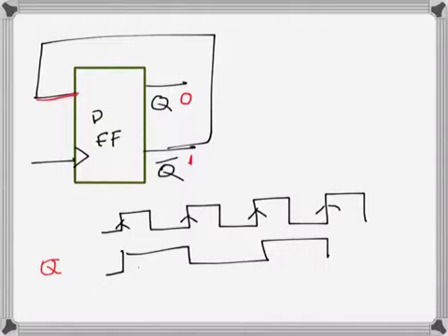With the first clock, D is getting 1. So Q will become 0 after that, and this will keep going on. So this is the wave shape of Q, assuming there is no propagation delay. If there is a propagation delay and we consider the setup time, what happens? Let's assume that with the propagation delay, this one goes there and keeps going like that.